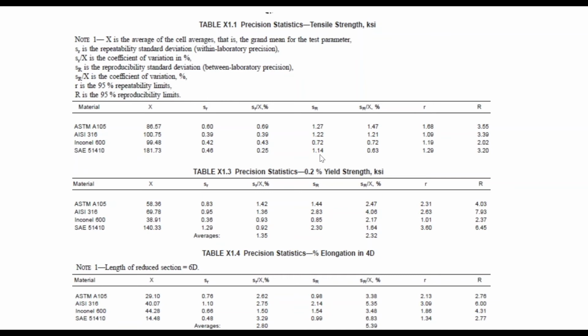So these would be the numbers you would use if you were talking to a customer who was measuring the same test bar you measured, but of course he can't. So you have not only this problem, you also have the other problem. If we really wanted to do something in ASTM, just like we have product analysis tolerances, we probably ought to have mechanical testing product analysis tolerances, which would say that if my customer gets a value that is within 3.5 KSI of the minimum requirement for an ordinary steel, that probably should be a pass.